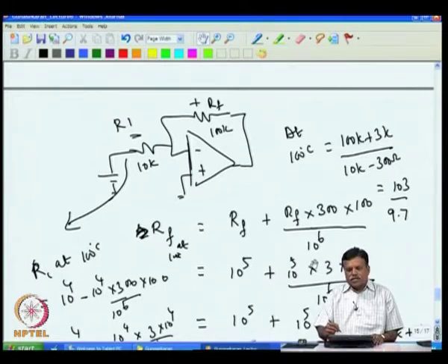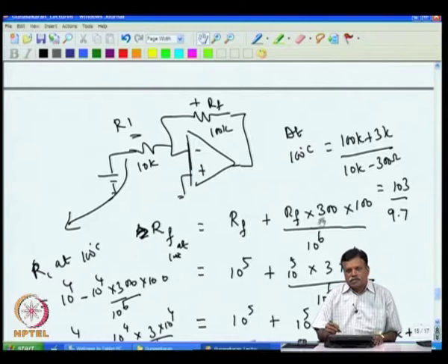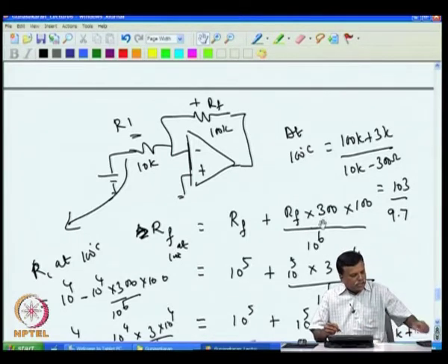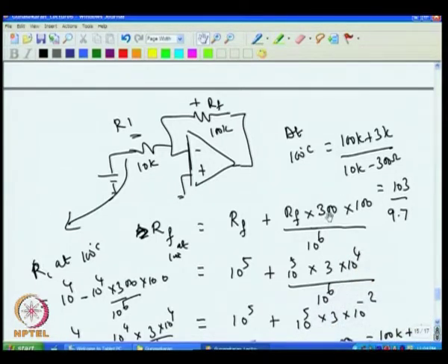So, you have resistors of various values available, right from 10 ppm to 300 ppm, and of course, cost goes up. When you look for low drift, automatically the cost goes up. So one has to make a compromise; whether you need a low drift resistor or not depends upon the application.